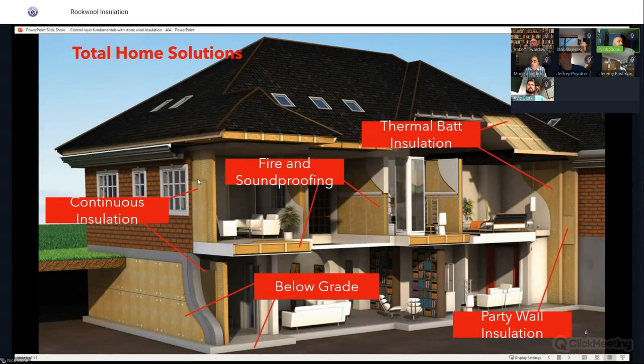Which is going to be that above grade portion of the wall. That's typically where people think of us, but we're also now designed for below grade application as well. So if you want an alternative to foam insulation, this is a nice option. You don't have the leaching of chemicals into the soil. We don't have issues with the bugs, in particular the ants, like some of the foam products. And you can also use this for below slab.